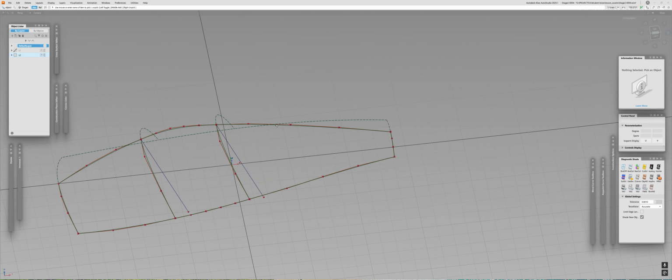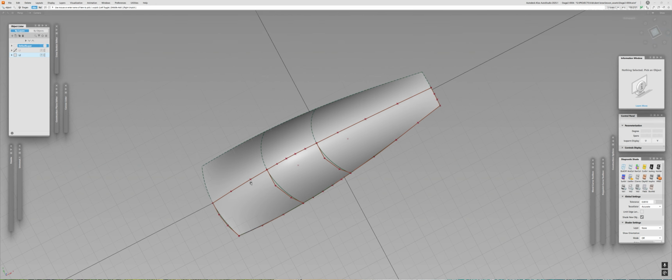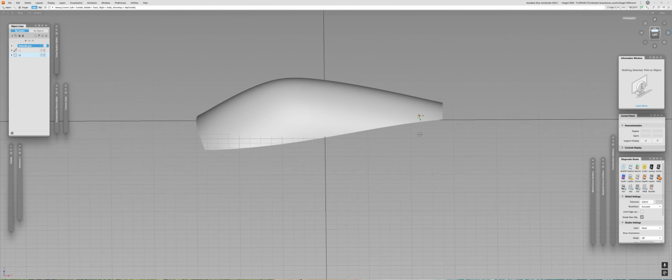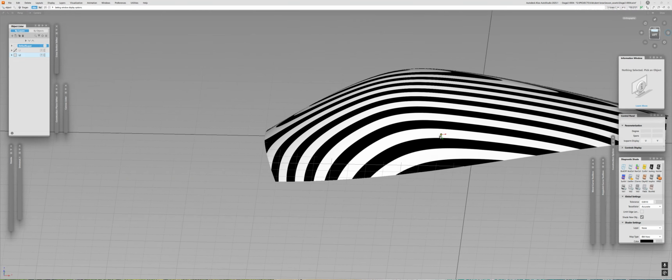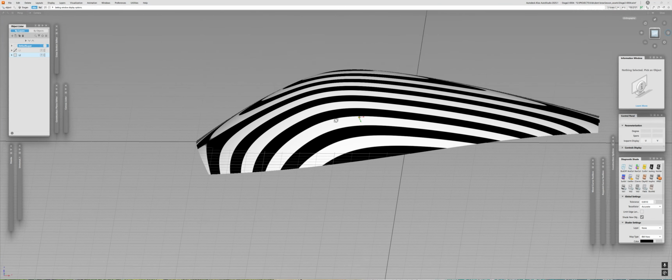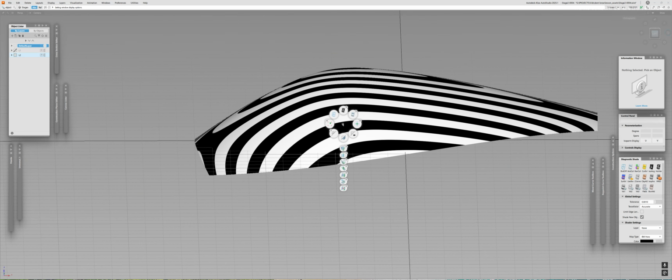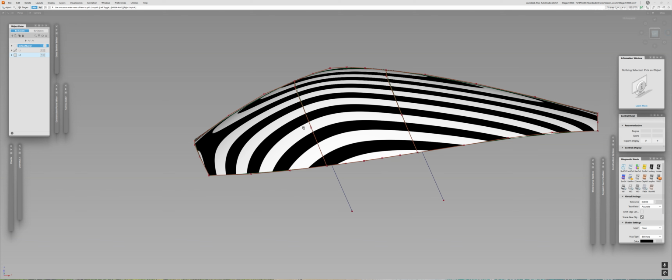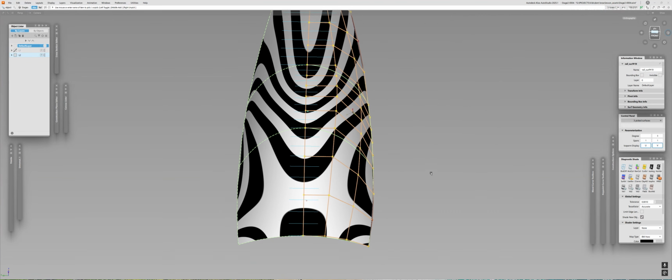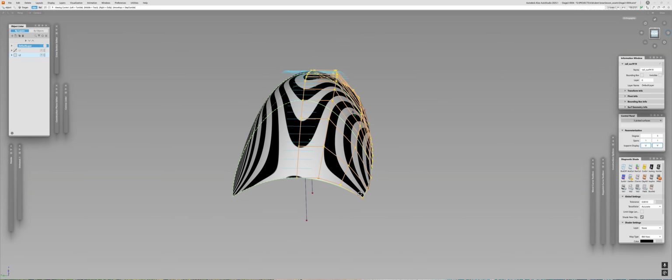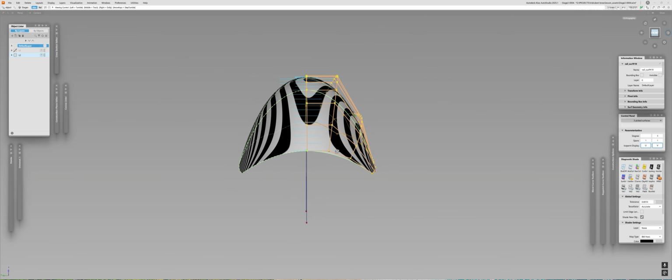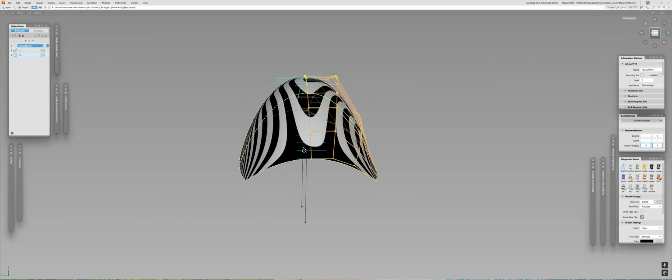So that's basically it. Now we created all the pieces, and here we go. Let me just activate the zebra stripes and look closer at what we get in return. Now, one important note I already mentioned before, this is not technically an A class surface, but this is really good as a starting point. So you started with your concept design, you have your sketch, you created the proper curve network, or you created the surfaces, and if you're pretty much happy with the surface you have, happy with this somewhat aggressive pinch on the sides, right? Which actually looks quite cool. I like it.